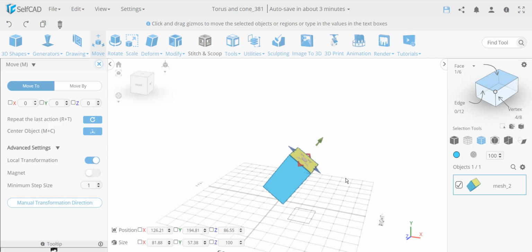Now this works very well when you're working with a single face because it's easy to use, because this is planar. It's called planar, meaning this is flat, it's a plane. The same way I can use the grid as a plane, I can use this face as a plane, face or polygon, whatever terminology you use. We'll discuss this in a different video. But for now, the main concept is that it's flat. Because it's flat, I can use this to give me the axes, the coordinates, and align the gizmos with this as a form of local coordinate system.